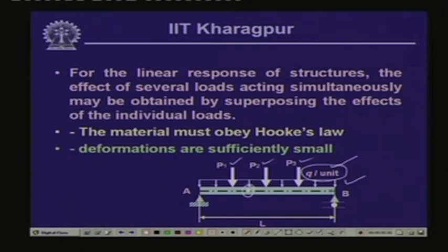Let us say the usage of the differential equation of elastic curve. We can use the differential equation of elastic curve, which says that EI d2y/dx2 is the bending moment M, and we can employ that to evaluate the deflection at this particular point for the general loading as shown. Also, we can evaluate the deflection of this particular point using the method of superposition, wherein we use individual loading. Instead of considering all the loadings acting on this particular beam, we consider the loads one by one and evaluate the deflection at this particular point for each individual load, and finally we sum them together to get the final deflection at this particular point.